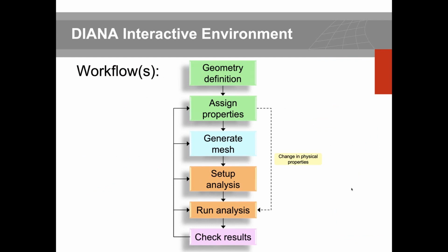In terms of workflow, we start with the geometry definition, always the geometry definition in Diana IE. Then you assign your properties in terms of material, boundary condition, and loads. You generate your mesh, so you assign your mesh settings and generate your mesh. You set up your analysis.